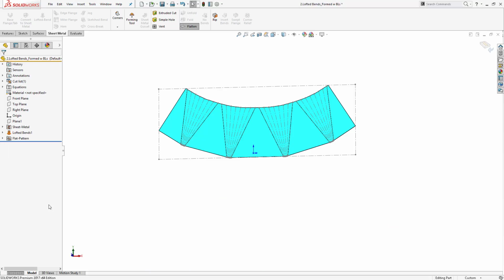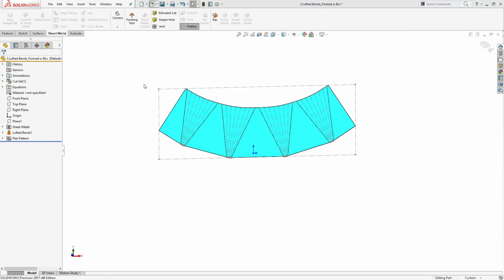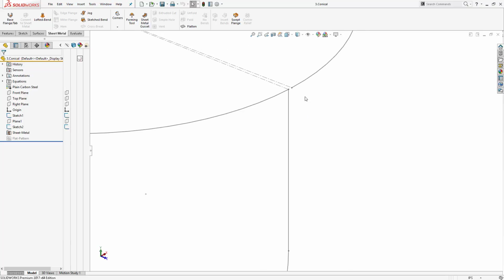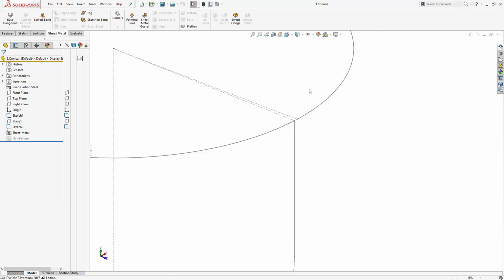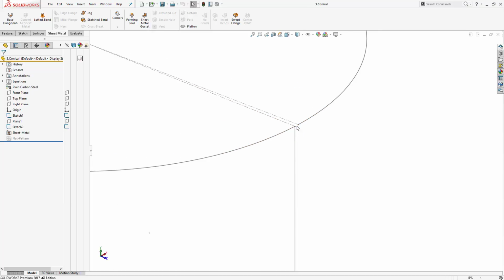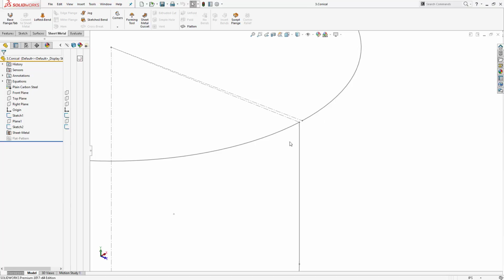Right, swept flanges. We were talking about that first one, conical swept flanges. The first thing to note about a lot of these swept things, as you saw in the lofted one, is that you need to have a gap. Hopefully that's known, but if not, that's how it works.